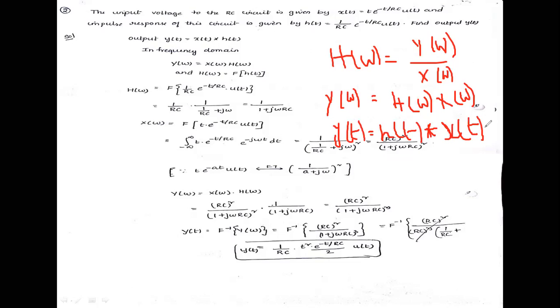The two signals are given, so you can either apply convolution, or find the Fourier transformation of x(t), find the Fourier transformation of h(t), and take the product of H(omega) and X(omega), then apply the inverse Fourier transformation of that function.